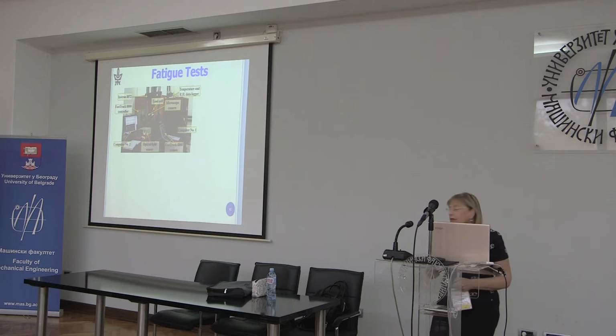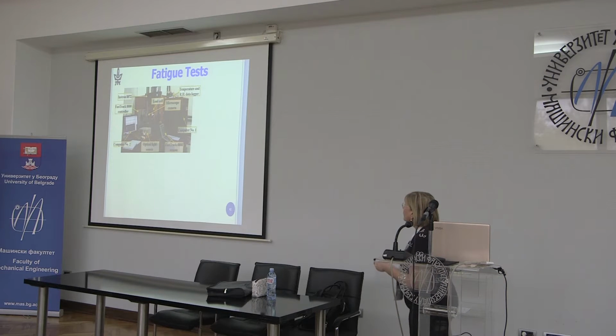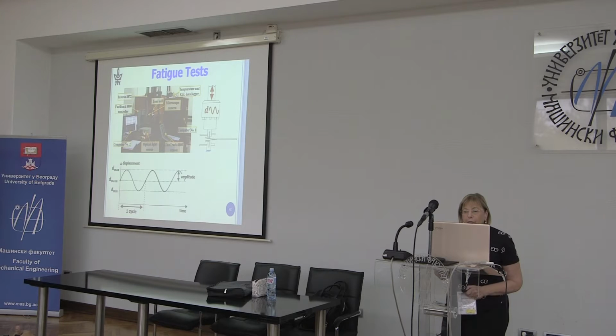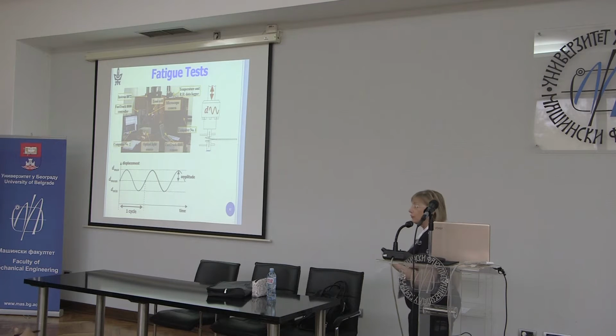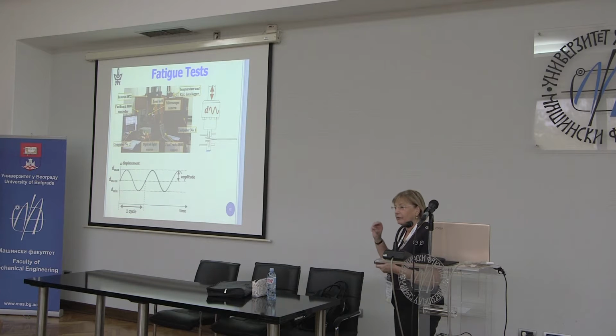This is our fracture toughness, but it's a function of crack length. And we carried out the fatigue tests in our loading machine, and you have all the details here, which I think I'll just skip along. The loads are so small. The load cell here, for example, is 250 newtons. These specimens take very small loads to propagate. In the fracture toughness test, the maximum load was around 60 newtons, and here we get up to around 40 newtons, and it just decreases.